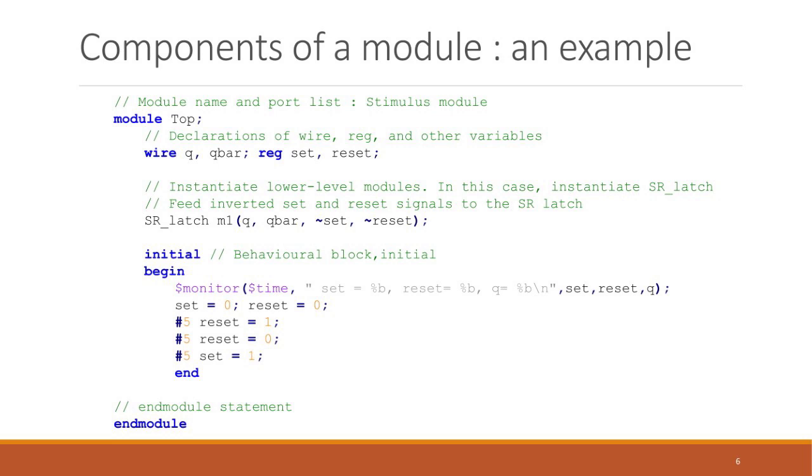So finally, whenever a signal changes its value, a new line with the simulation time and the signal values is printed to the command prompt. After that, you can see we assign different values to the set and reset inputs with time. And when we simulate this test bench, we should be able to see new lines getting printed for each signal change that we are doing here.